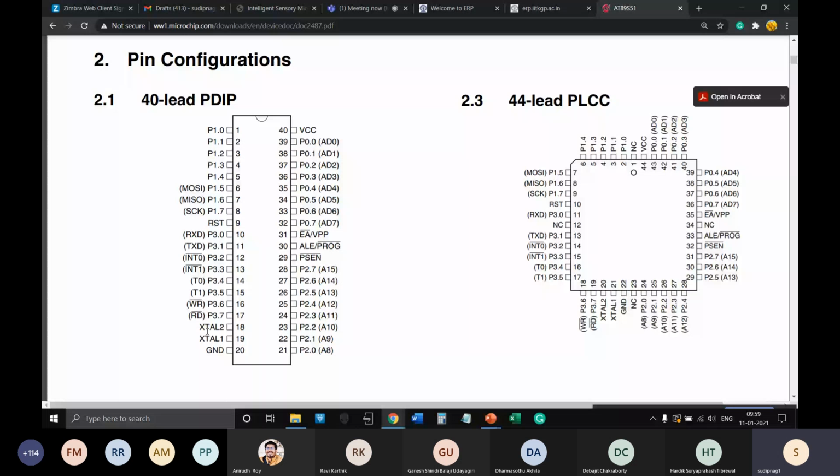So crystal oscillators are typically adopted in the 8051 and most microcontrollers. The crystal part is outside, which is a separate device, such as a quartz crystal, and the crystal oscillator circuit is inside.